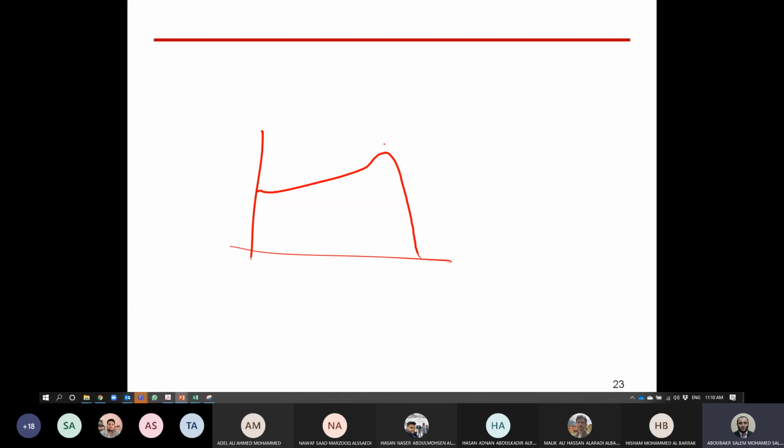This is characteristic number 1. S maximum here should be the value which is corresponding to T maximum, which is here. Here, assume that you have NS equals 1800. If S maximum is 0.2, what is the speed at the value of S maximum here? What is the value of speed in this point?